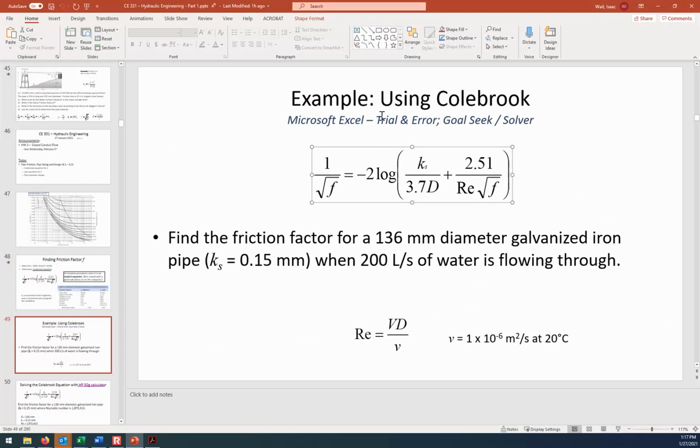You know, you could have just done these calculations on paper. If you were in the classroom with me, I'd hold up where I did this same example just kind of by hand, where, you know, in your calculator you take a guess value of f, you put it in the left-hand side of the equation, put it in the right-hand side of the equation and see if it matches, and then try a new value of f.